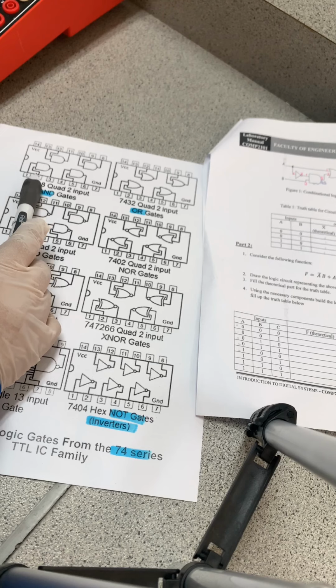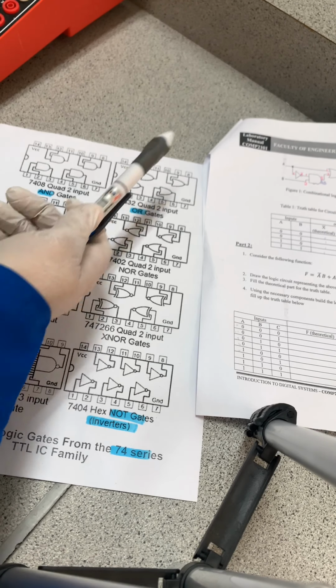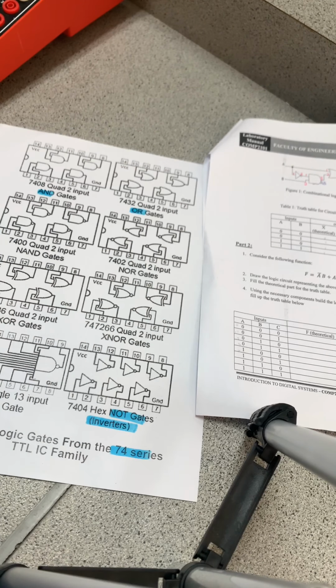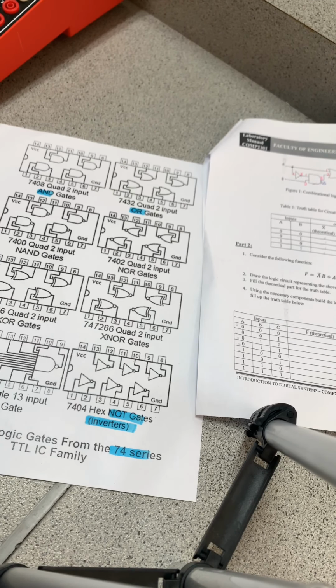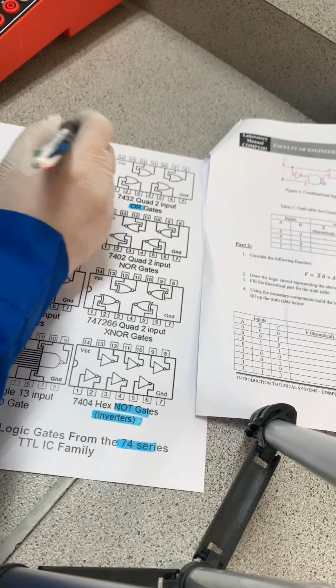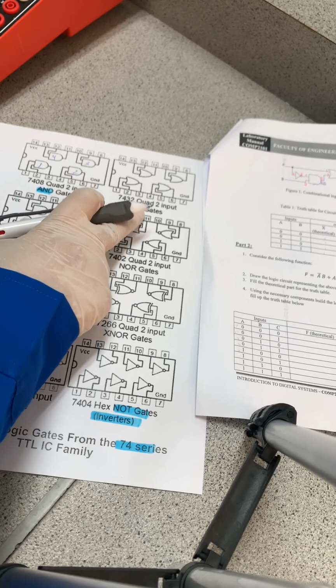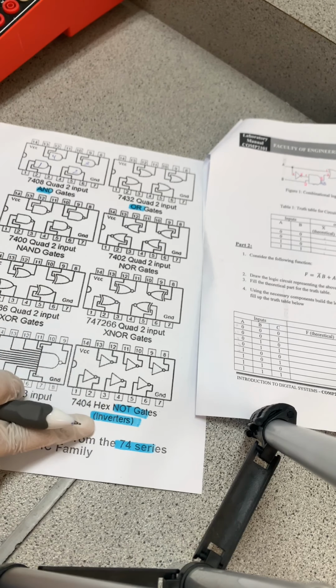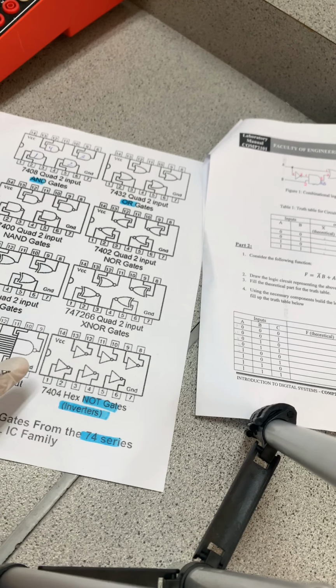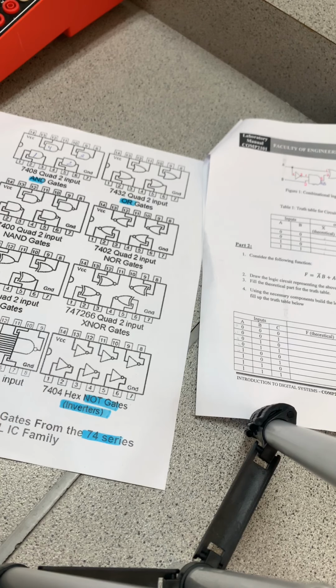You have to know that if you need another AND gate, for example, in part 1, I need just one AND, one OR, and one inverter. But if you need a second AND, it will be the first AND, second AND, third, and the fourth AND. Again for the OR gate, and also for the inverter, I have 6 inverters here. The inverter has pin number 1 as an input and pin number 2 as an output, so you have one input only. But the AND and OR gates all have 2 inputs.